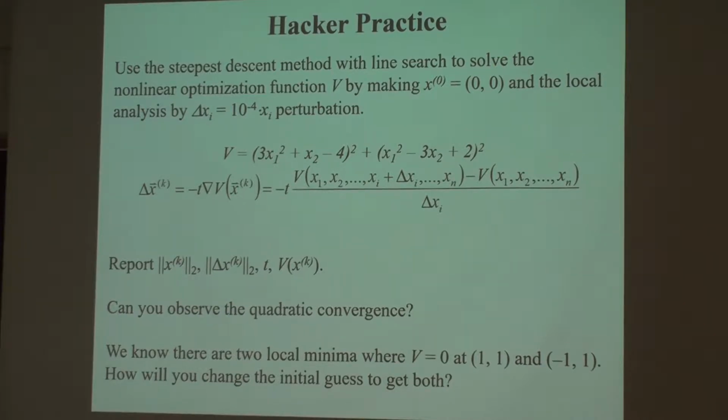Because you want to do two things. First, you want to be C infinity, so it's always continuous. Second, you want to be able to estimate your leakage power. When it's off, nothing is really off. How much it is off is captured here. So that today, in any circuit design, the static power consumption is the number one consideration. If you are still learning that the transistor is off and you can ignore it in the circuit, you live in the last century. So know how transistor leakage is captured here.